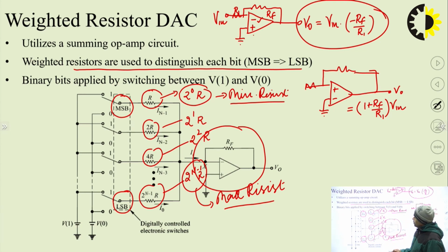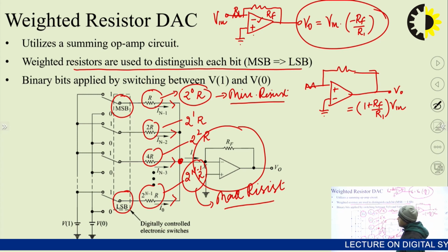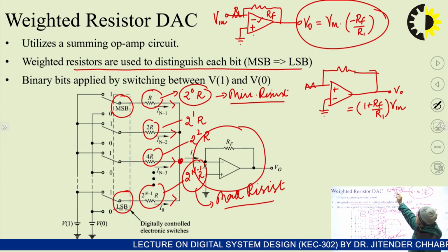We can see that in this scenario the op amp terminal is the aggregate of multiple input terminals. That means voltage will be reaching this terminal from multiple inputs, and the aggregate will be considered as the input to the op amp. In all these cases input resistances are different, which we mentioned here as R1.